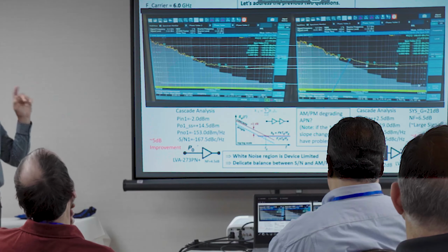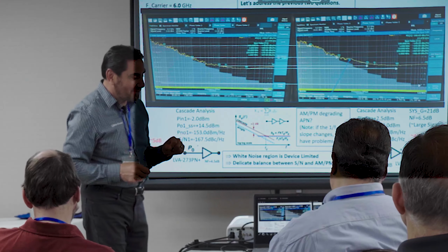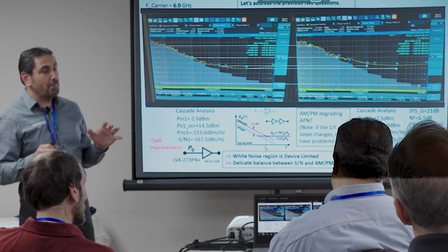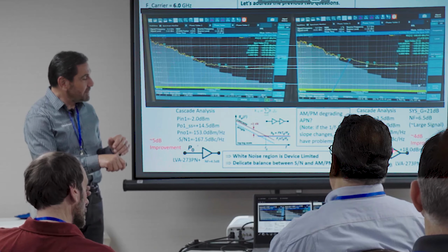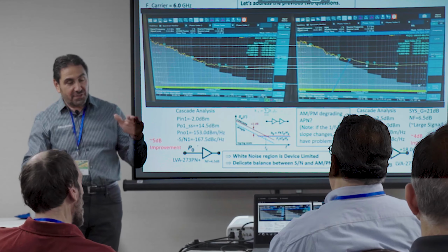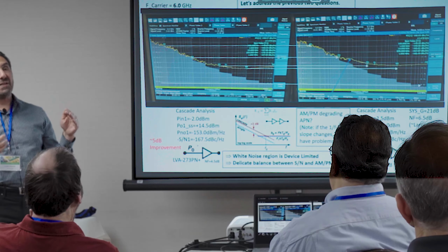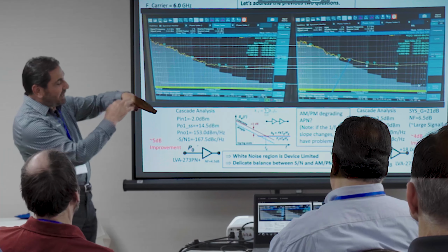I didn't talk about one feature of my favorite reflectionless filter. What you'll find when you do this over a wide band is that sometimes this input power over frequency wants to get less to avoid going into those high AM to PM regions, which means you need to slope your input power to have a negative going slope.